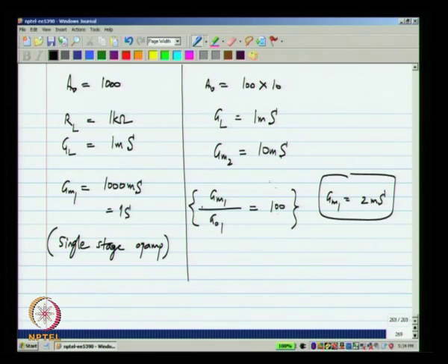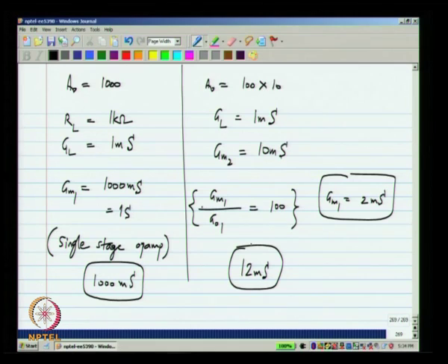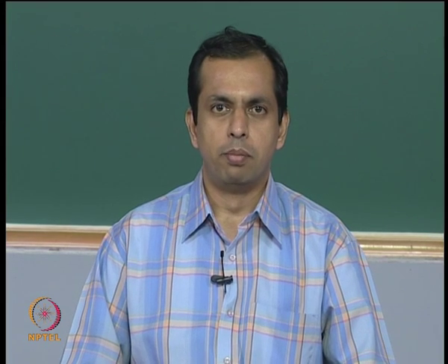Okay. So, clearly in this case we have to realize a total transconductance of 12 millisiemens, and here the total is 1000 millisiemens. Now, of course, how much power we burn to realize a given transconductance depends on the topology, but just from the basics of MOS transistors we know that if you want a larger GM, you have to have larger transistors operating at higher currents.